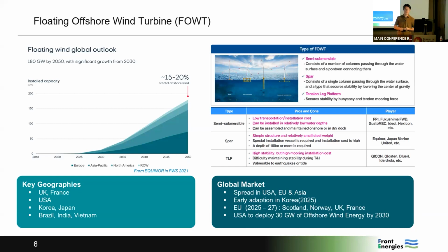So up to now, in the offshore industry, we can say that around four characteristic floaters are available. One is the ship shape. The other three are the semi-submersible, as we can see, the semi-submersible shape, and the spar shape. Spar is just a single pipe, a very long single pipe. And the other one is the tension leg platform, TLP. So three different floater design concepts can be applicable to the floating offshore wind turbine.